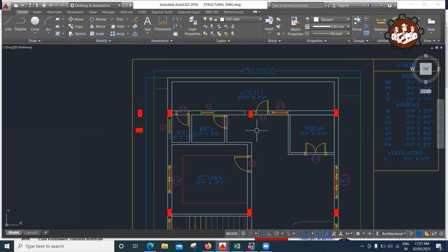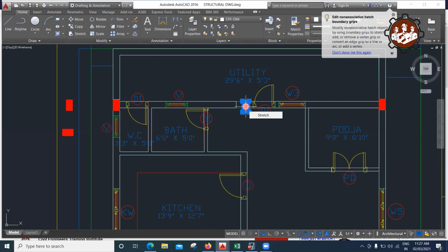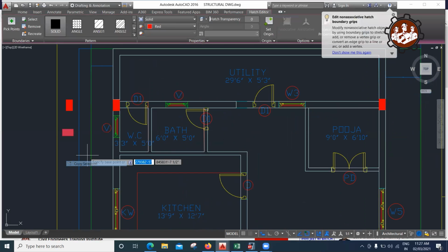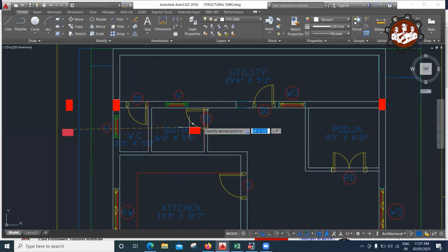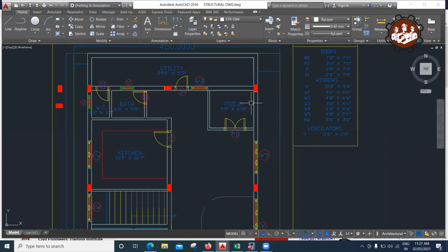So what we can do is try to orient this column now, right? Instead of this, let me delete this column again. I'll take the horizontal column so that there is no offset created. Let me try to keep the column in this way. Yeah, done. This is not creating any offset because this will be flush with the wall. Now if you look at the columns, they all are good.